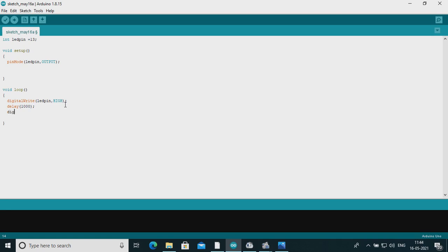Then again digitalWrite, LED pin, LOW we will do. Delay, again we have to pass a delay. This delay again 1000 milliseconds. Okay, this is done. This is the programming of glowing the LED.